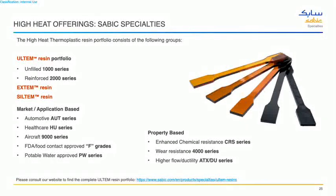And this kind of material is also a very good flame retardant material by itself. That's what you call LOI, limiting oxygen index. So this was a very good flame material. But nowadays people like to use materials that are PFAS free, and these kind of materials could be very handy to stop the flame propagation, with good ratings. And there are a lot of markets here, starting from automotive, healthcare, aircraft, food contact, and some very niche applications, and these are unique materials for the high end of engineering thermoplastics.